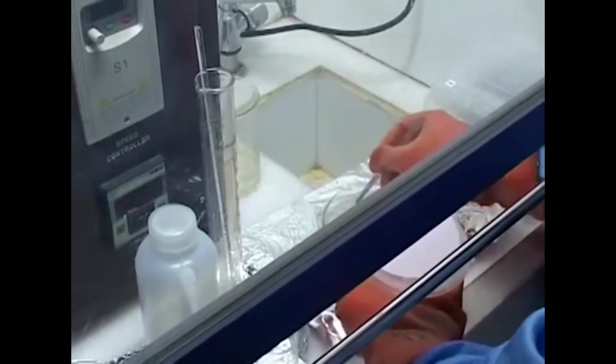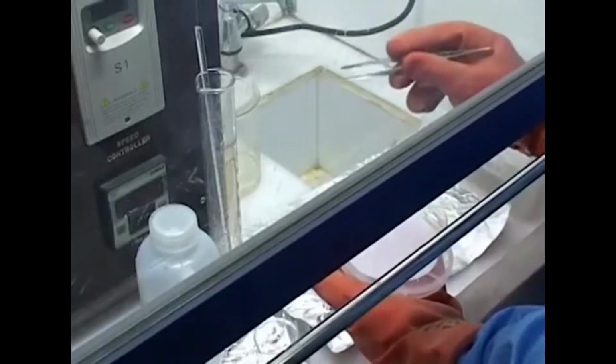Okay, and once we pour the Piranha, we can no longer use this metal tweezer for handling this wafer. So we'll have another separate Teflon tweezer for handling the wafer once it's out of the Piranha for washing and rinsing.